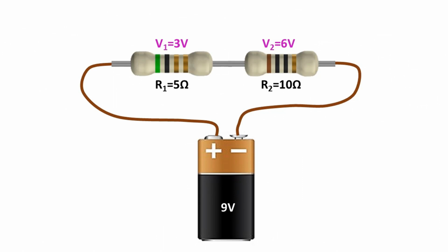Even if more resistors were connected in series, we would have to calculate in the same way. We can calculate the voltages on the resistors in this way without finding the current value. In addition, the total voltage consumed by the 2 resistors gives the source voltage. Otherwise, we would have miscalculated. This is the working principle of series-connected circuits.